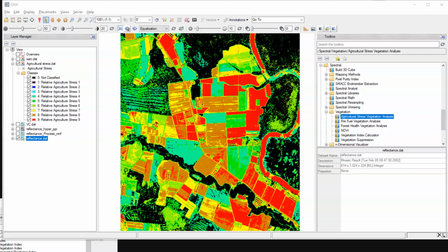So now, working with DEMs. The DEM is generally, as we know, used for extracting the terrain parameters for geomorphological studies, hydrological modelings, and many more. For DEMs, ENVI provides general tools that can be used for analysis of such topographic data sets. A variety of DEM-specific tools are also provided for processing digital elevation data to generate geomorphic measures such as slope, aspect, shaded relief, profile convexity, plan convexity, and many more.